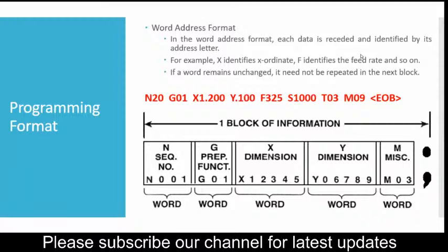old, and the word address format replaced them all because of its wide adaptability, and reading of the part program and preparation of part program would be easier. So in word address format, how do we program? Every number, if you see 20, 0, 1, 1.2, 0.1, every number is preceded by some alphabet.